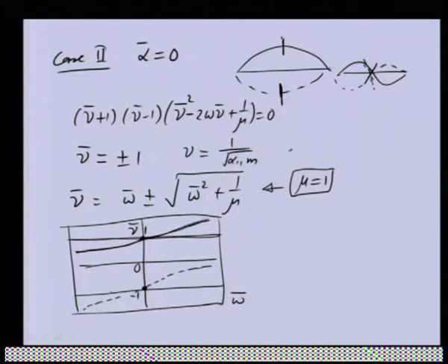So you can see that at one particular omega, apart from the 0 spin speed, if we draw a vertical line, we get 4 intercepts: 1, 2, 3, 4. There are 4 whirl frequencies, but two of these intercepts represent the same one. For positive omega we get 4 intercepts.